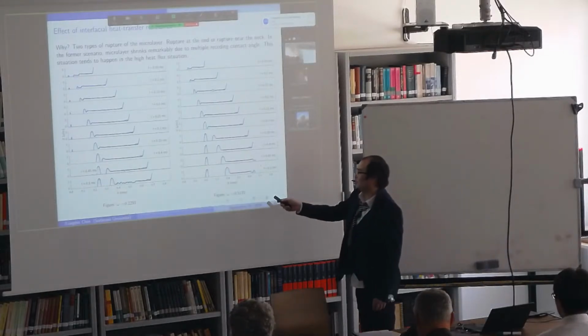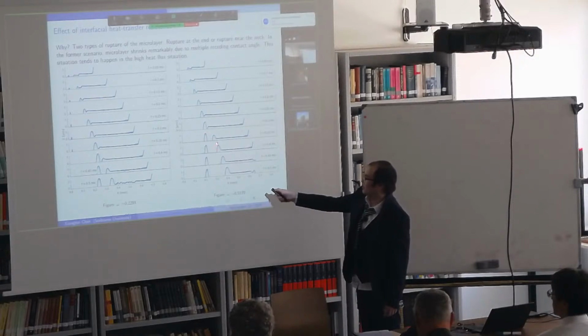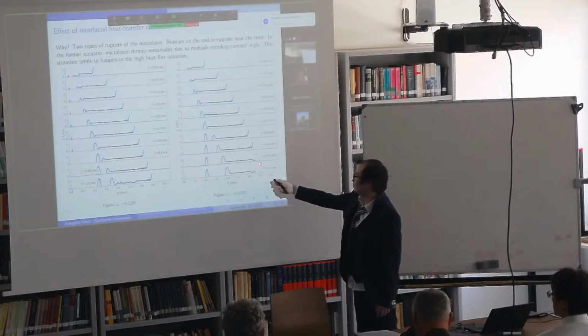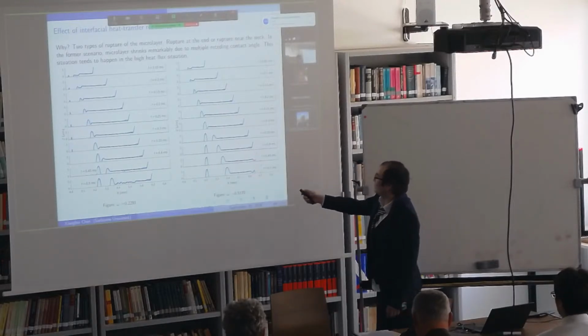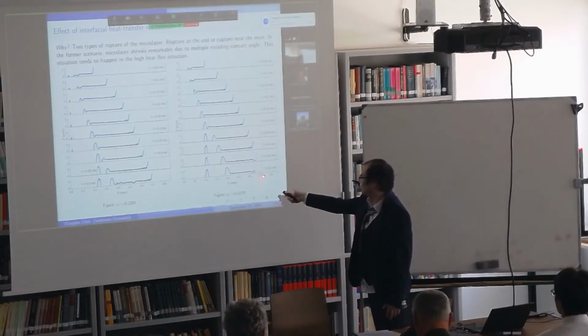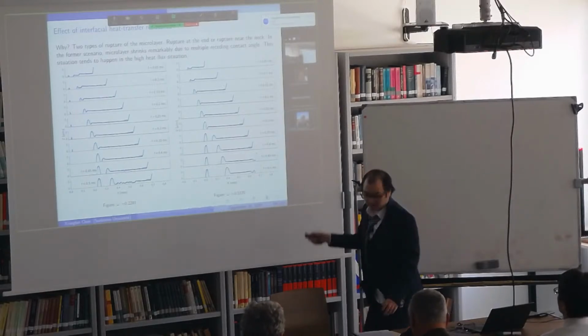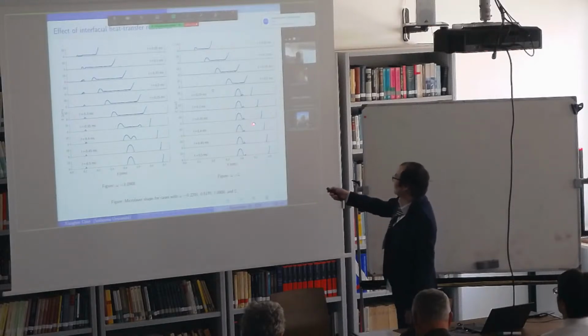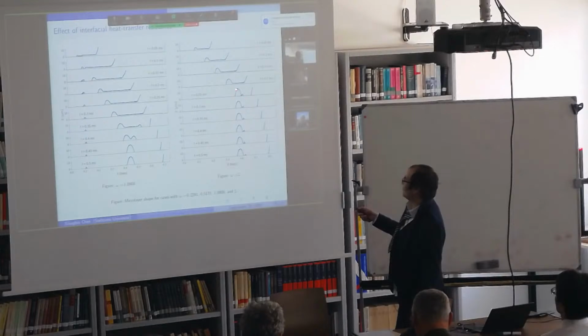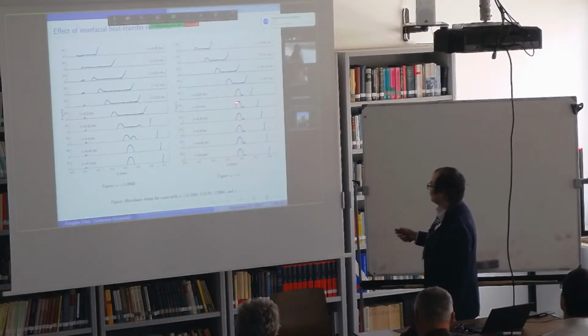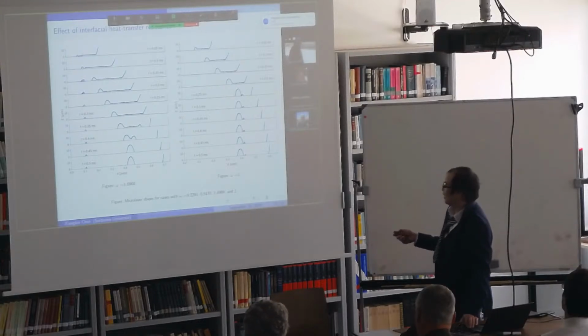So you have two types of rupture. First is the rupture at the beginning of the microlayer, which is almost at the neck. And the second type is that the rupture is at the tail of the microlayer. For the impact, the later rupture is more significant, because if you rupture at the tail, then the long microlayer has two ends of the triple point, and because of the receding of the microlayer, it will shrink to a bump. This significantly shrinks the length of the microlayer, and then it will affect the heat flux contribution to the whole bubble. Then the growth rate will decrease.